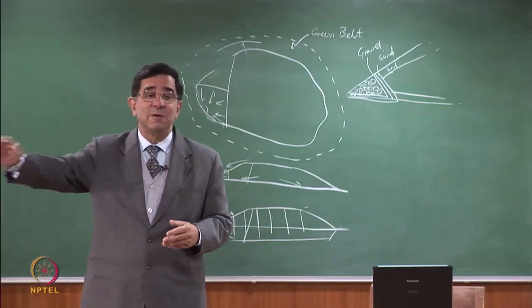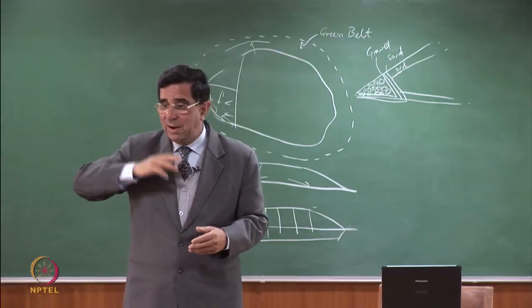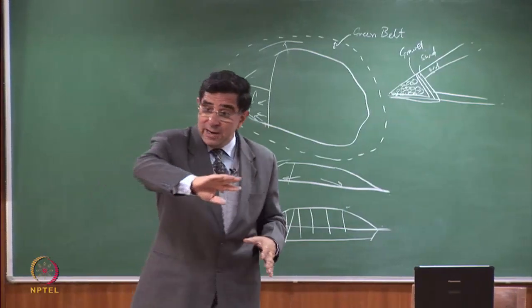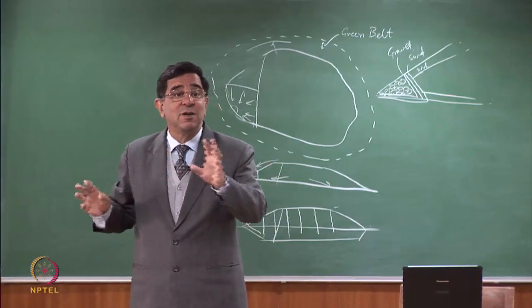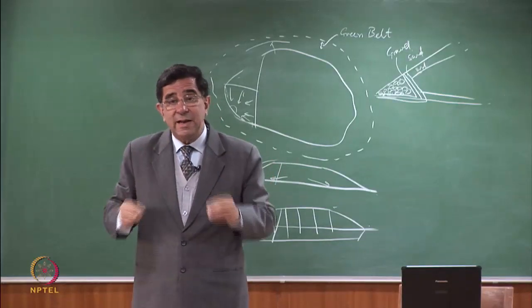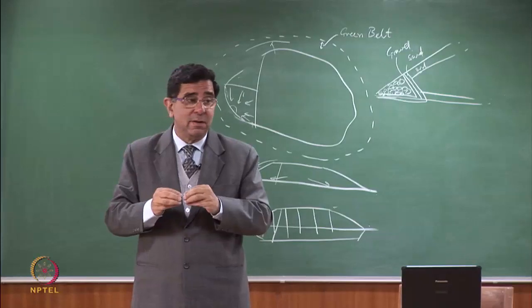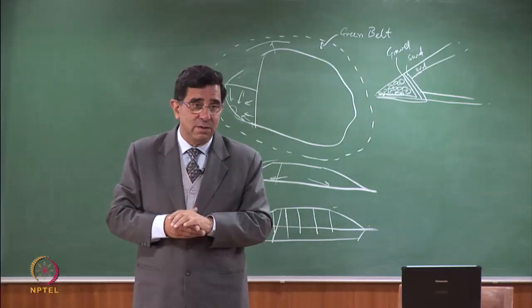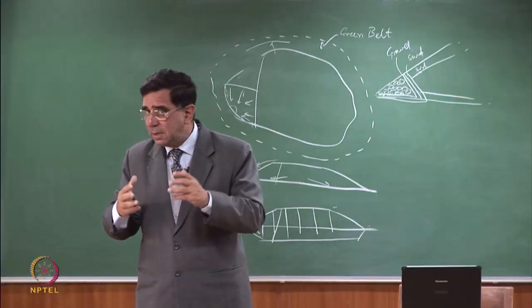There the excavation is taking place, the clay liner is being laid, on top of that the geomembrane is being laid. And all the area after that is still the original scrubland or the original shrubbery and the trees. And in that you have your surface water drainage systems. You don't want any water to come into the landfill. So that's typically a good design.